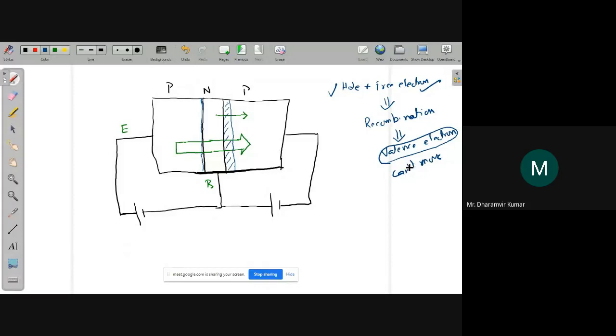So we have lost some amount of electric current because of this recombination process. When holes enter the base region, a small portion of them will recombine and turn into valence electrons. I will show this by a very thin arrow, signifying that the rate of recombination occurring here is still small compared to the thickness of this arrow. Whatever is lost here has to be supplied by these two batteries, and that will result in a small amount of current flow through the base region.